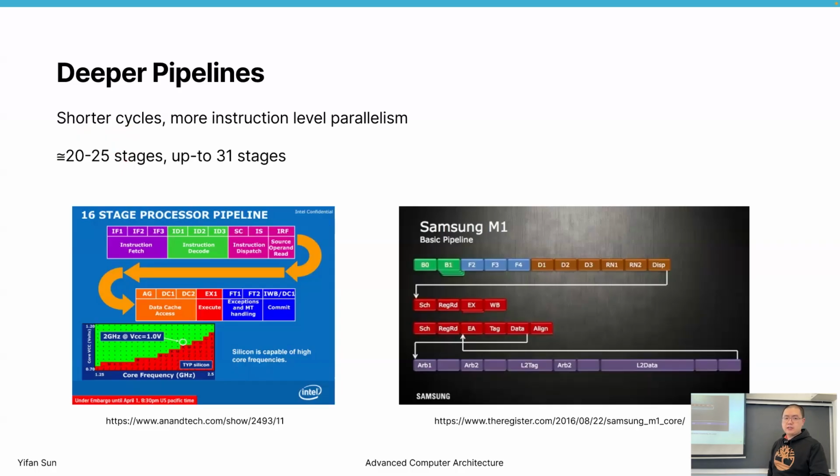And by the way, in today's phone or laptop, there are typically two different types of cores. There's an efficient core, which has a really small die size and really low energy consumption. So when it's running some task that is not very performance critical, it will select the efficient core to save battery and save energy.